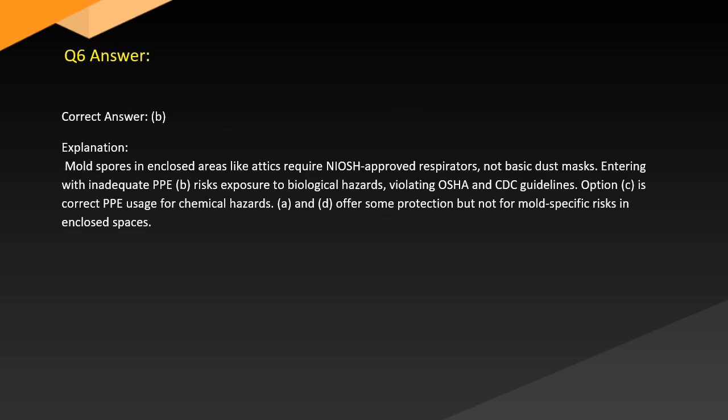Answer. Correct answer: B. Explanation. Mold spores in enclosed areas like attics require NIOSH-approved respirators, not basic dust masks. Entering with inadequate PPE, B, risks exposure to biological hazards, violating OSHA and CDC guidelines. Option C shows correct PPE usage for chemical hazards. A and D offer some protection, but not for mold-specific risks in enclosed spaces.